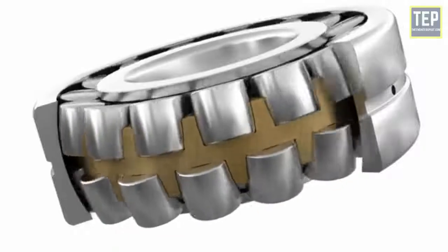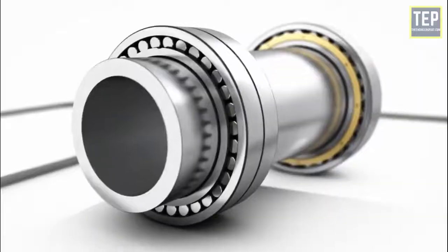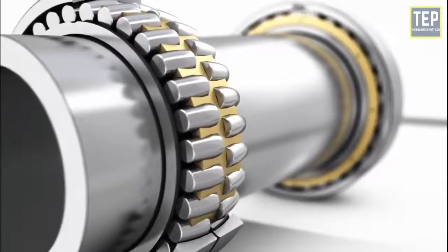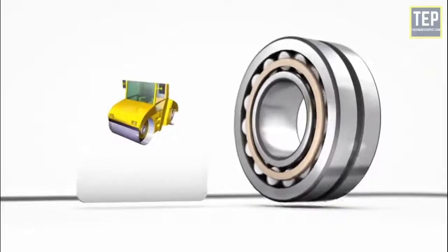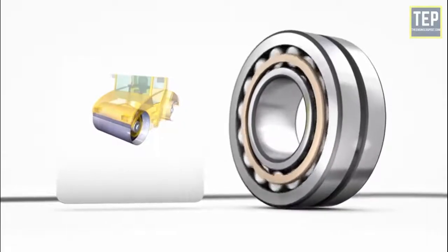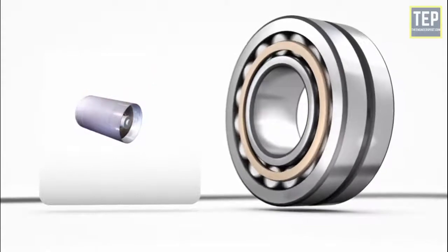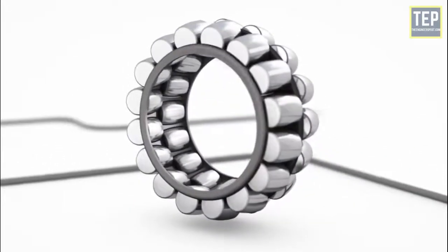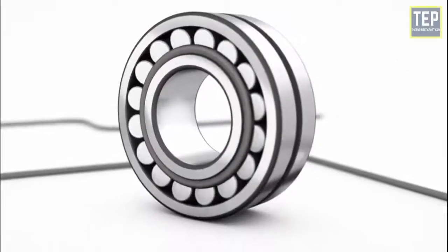Roller bearings maintain accurate alignment of every part over a long period of time and can carry heavy momentary load. This renders them suitable for machinery that requires frequent starts and stops. Rollers make line contact with their races, while balls make point contact. It has a higher load carrying capacity.